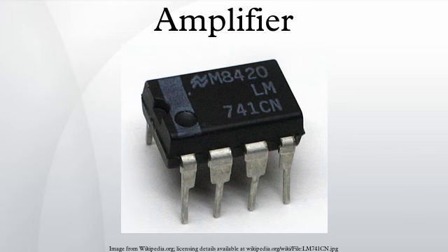Class G amplifiers are more efficient than Class AB amplifiers. These amplifiers provide several power rails at different voltages and switch between them as the signal output approaches each level. Thus, the amplifier increases efficiency by reducing the wasted power at the output transistors. Class G amplifiers are more efficient than Class AB but less efficient when compared to Class D, however, they do not have the electromagnetic interference effects of Class D.